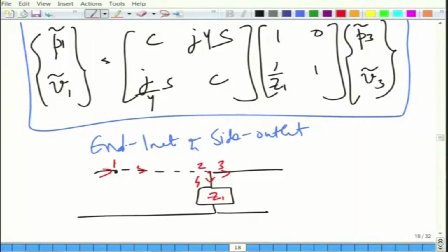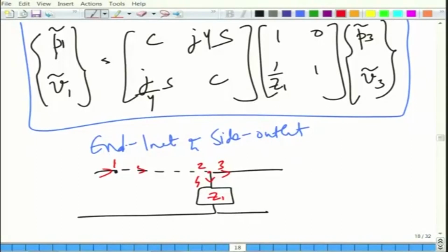So, why am I telling you all of this suddenly? Because if you change the positions of inlet and outlet, the transmission loss of such a thing will not change. And incidentally, using another representation named the impedance matrix, which we will cover probably in week 7 or so, we will talk about all these concepts perhaps in a little greater detail.